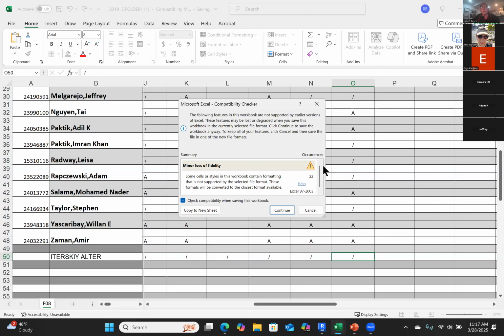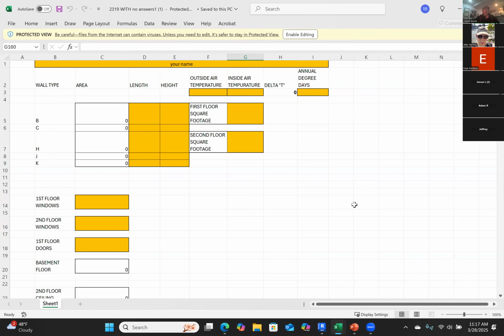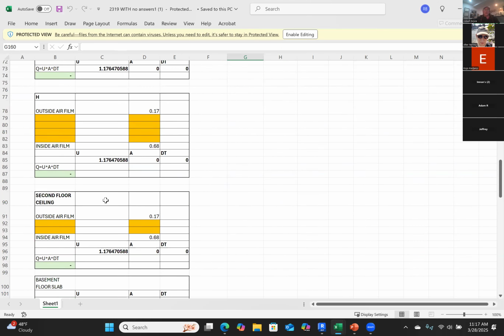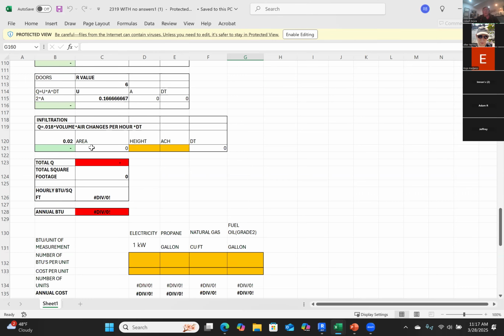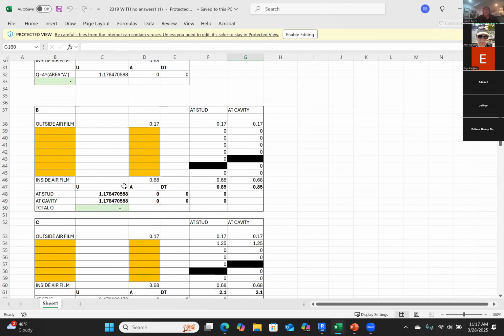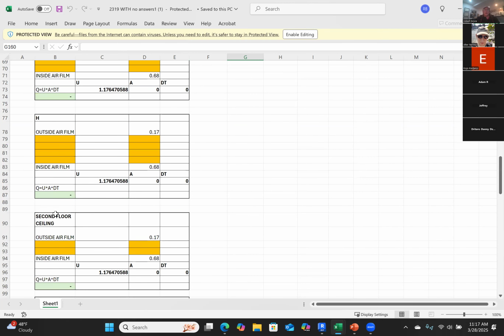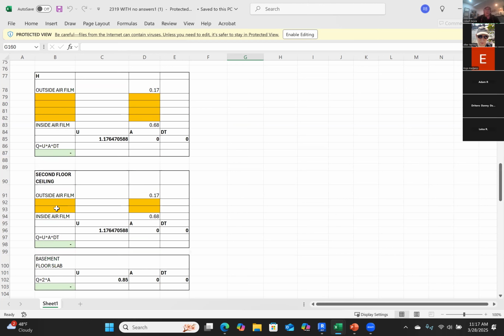Okay, so that's good for the attendance. The other thing is, if you have any questions about the project, we can talk about that for a couple minutes. Lisa came in to either office hours or a private Zoom meeting. We went over her numbers, and she was very concerned that her BTU numbers were really high. We noticed that she had failed to put in any kind of insulation in her ceiling, so there was a tremendous heat loss. And we talked about, what if you put 6 inches of fiberglass in your ceiling?